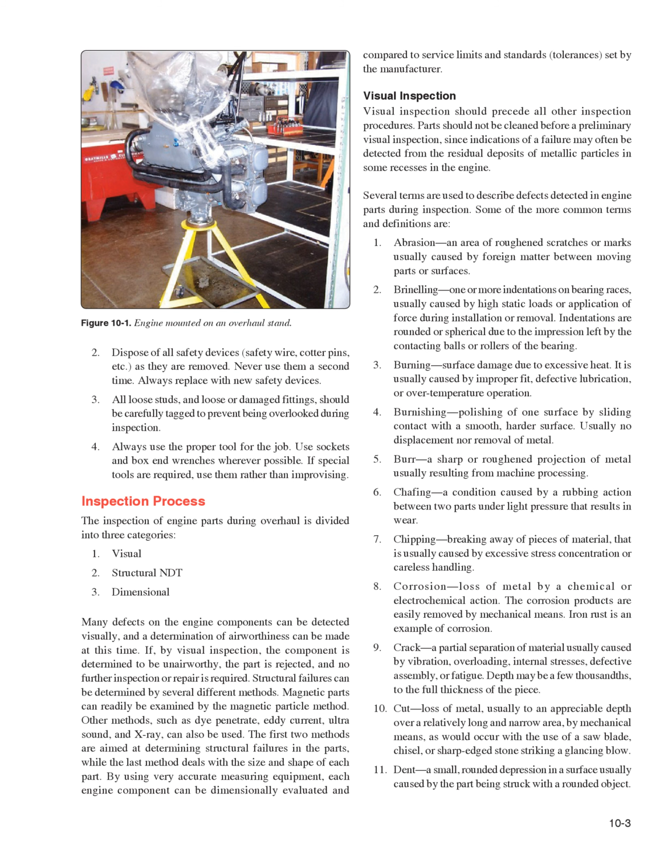Structural failures can be determined by several different methods. Magnetic parts can readily be examined by the magnetic particle method. Other methods, such as dye penetrant, eddy current, ultrasound, and X-ray, can also be used. The first 2 methods are aimed at determining structural failures in the parts, while the last method deals with the size and shape of each part. By using very accurate measuring equipment, each engine component can be dimensionally evaluated and compared to service limits and standards, tolerances set by the manufacturer.